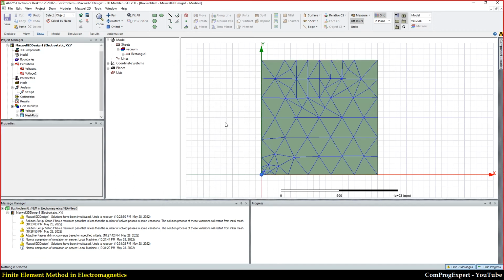So when we have continuity in Dirichlet boundary condition on our solution domain boundary, the convergence is achieved in few iterations. So in electrostatic problems, when we apply fixed voltage on boundaries of the solution region of our problem, we should care about these kinds of discontinuities, right?